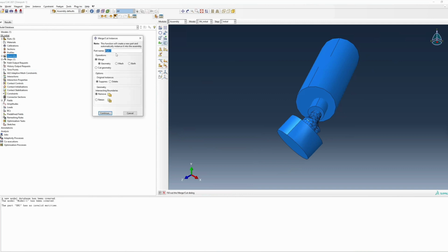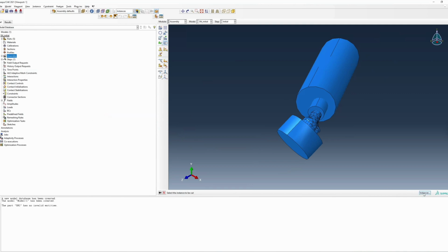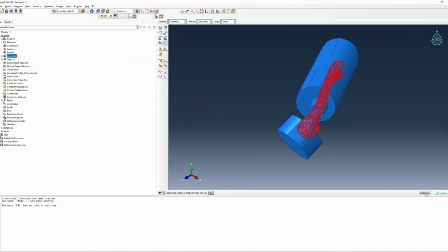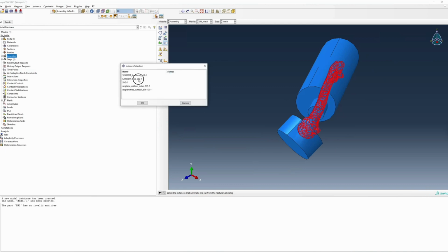As we begin our in-silico resection procedure, ensure that all your cut tools are properly positioned. Under the assembly module, cut your geometry and suppress the original instances. If you're planning on breaking up trabecular and cortical bone, I would probably suggest that you start off with a full bone model and a trabecular bone model.